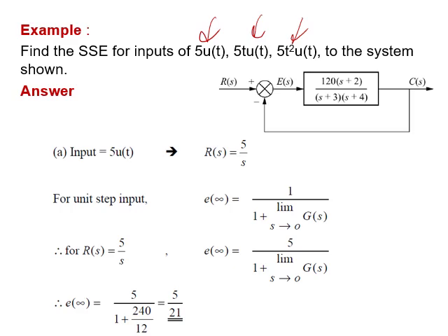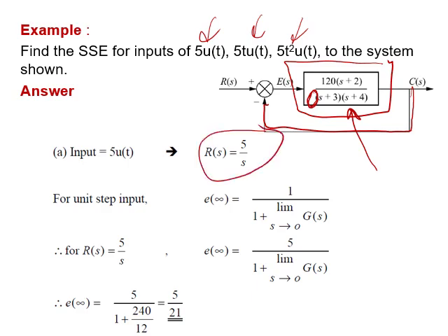The system, first of all, is unity feedback, where what is given here is the open loop transfer function. That's one thing to be noticed at the beginning. So I realized that we are going to get the formulas which we just calculated. Beside that, I found that there is no integrator here. If there is no integrator, I know before we start that if the input is step, we are going to get the error as a finite value. That we know before we start.